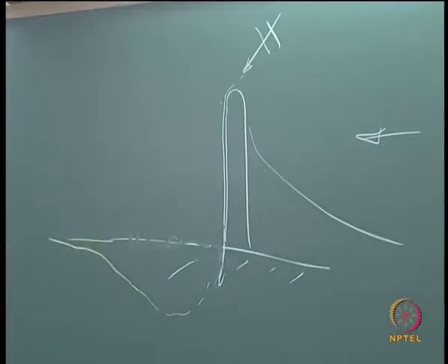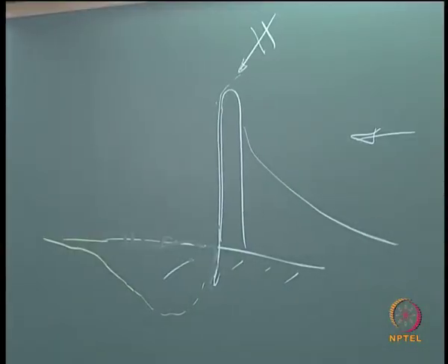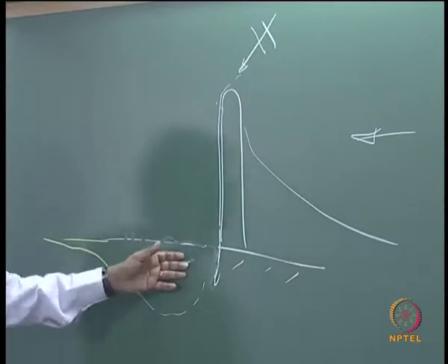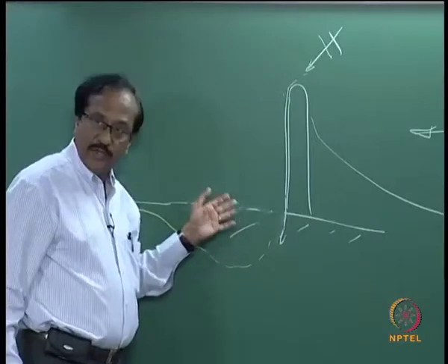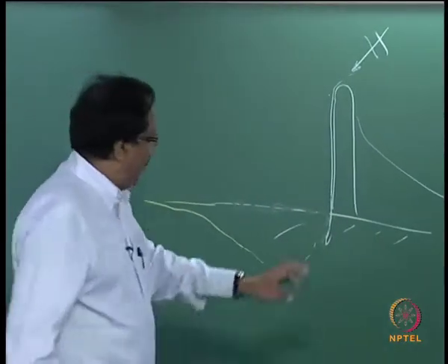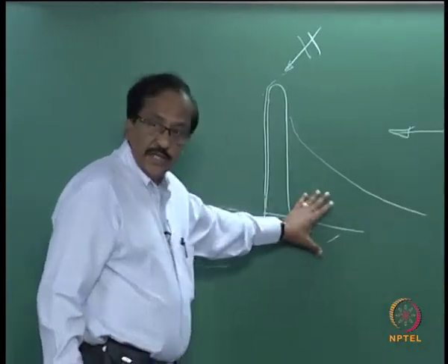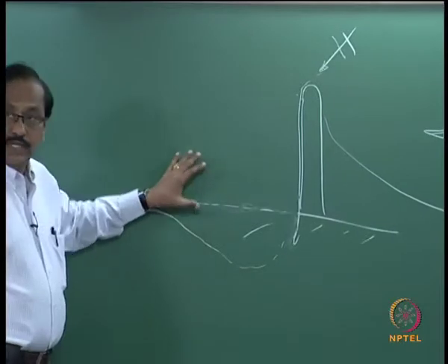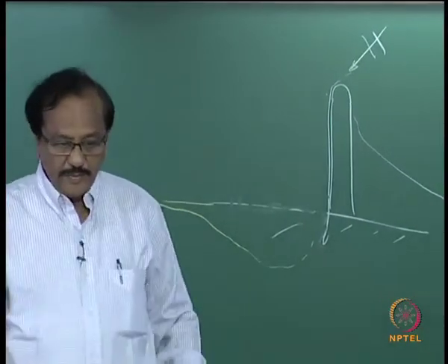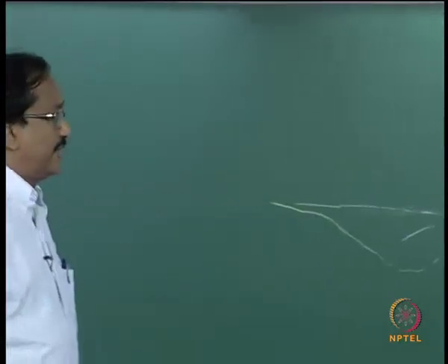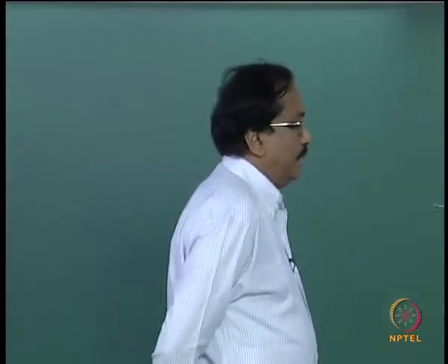So this is quite important, because if you put it in a location where you are not supposed to have erosion, then that is going to be a problem, okay. Although you will be preventing erosion this side, there is a possibility that you are creating erosion on the adjoining area. So this has to be borne in mind when you are planning for the construction of a groin.